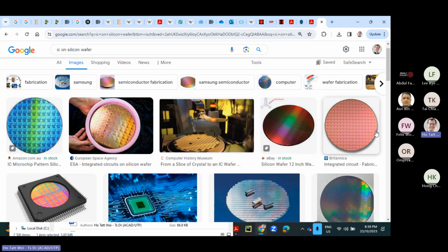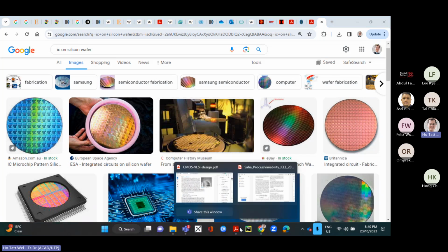You make one wafer, you make another wafer. Again, even though it's the exact same design, exact same photoresist, exact same mask, there will be variation in the performance of one wafer to another. Because maybe, again, a certain wafer you slice from the ingot. Sometimes when you slice, you will introduce certain stresses in the material, pressure or something like that, and that changes slightly the silicon properties between the wafers. Or for some reason, this wafer is slightly misaligned, slightly tilted in the machine, right? Or something like that. So there will be different sources of variation between wafers.